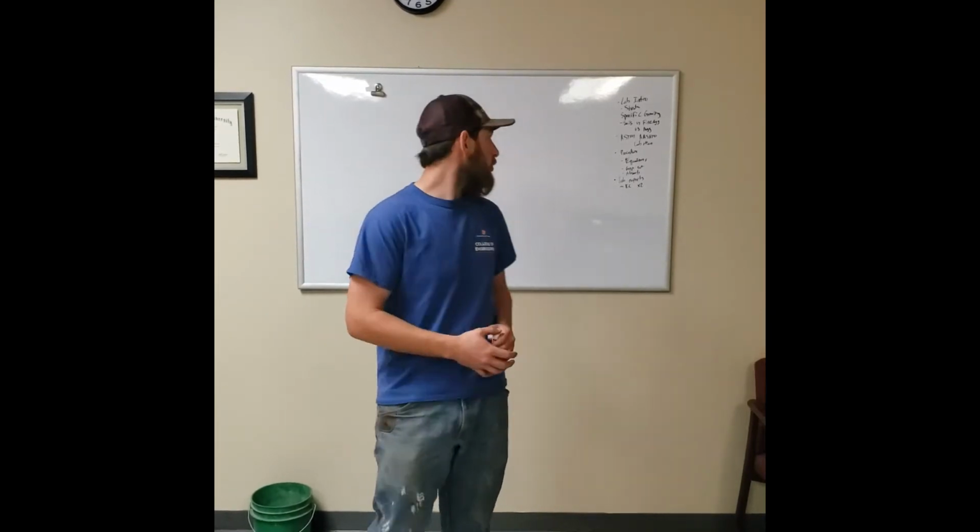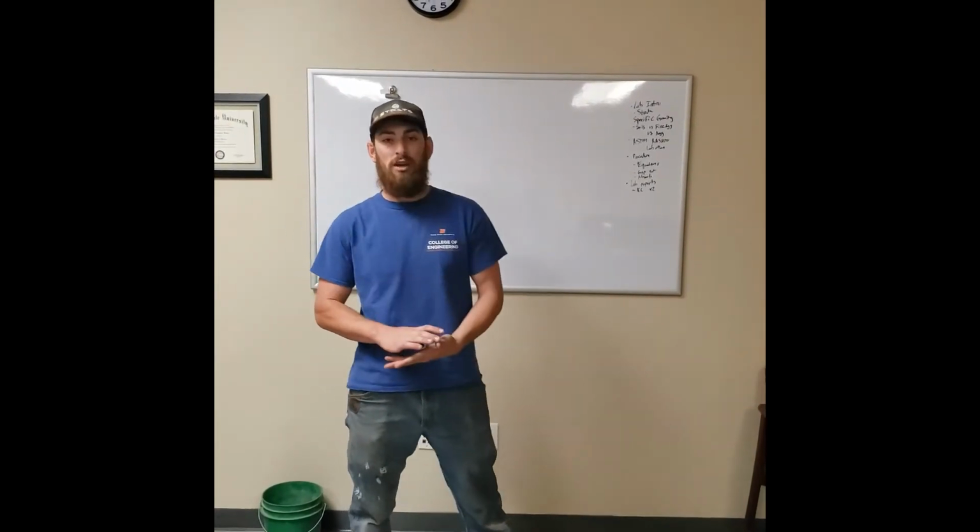So, specific gravity. Specific gravity is a unitless value that you use for looking at unit weights and densities. The way that it actually works is that you standardize a unit weight comparatively to the unit weight of water at a certain temperature. The convention standard is 20 degrees Celsius. So we'll be basically dividing out everything for a unitless value comparatively to water at 20 degrees Celsius.